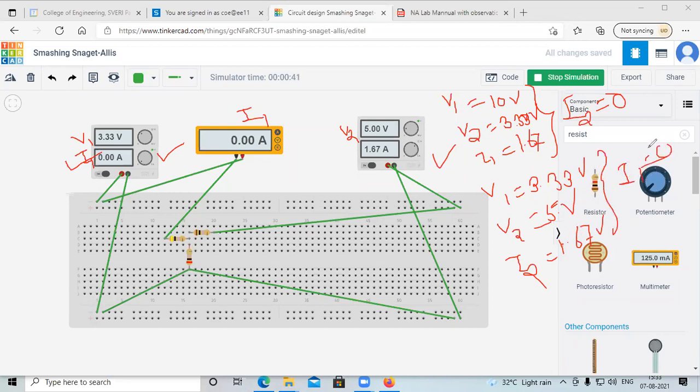All of you getting this? How the reading can be taken? When the input port is short circuited, you will get the 3 readings. When the input port is open circuited, you will get the 3 readings. And when the output port is open circuited, you will get the 3 readings.